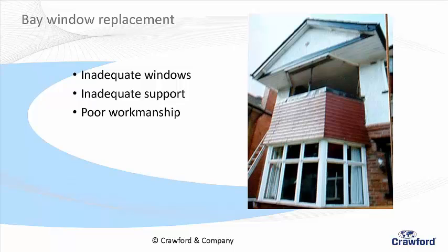Woefully inadequate for the kind of size that gave me. And they put that in. And lo and behold, she's got cracking on the apron wall inside here and on the other apron wall, and she's got cracking up at a higher level and into the gable. And I said, yes, great, but it's basically downward movement of that structure down to the replacement window. It's not the foundations, because this apron wall hasn't moved at all. Not one bit. Yeah?